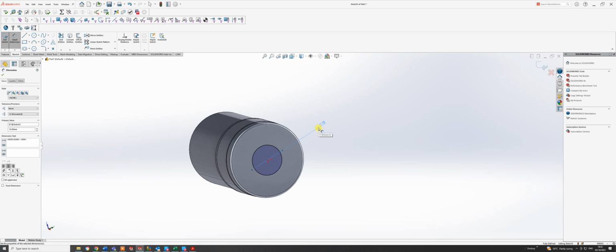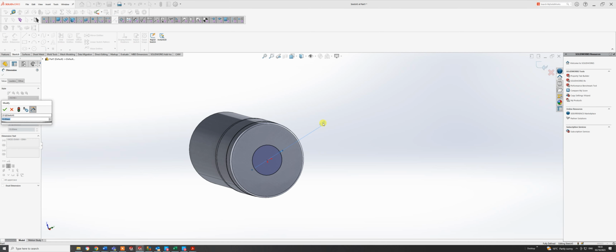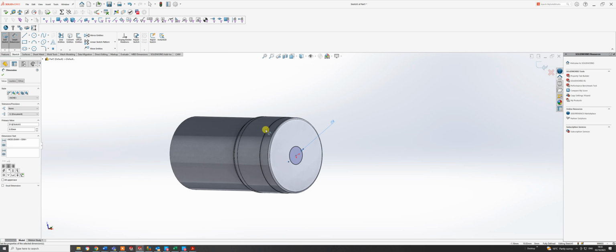It looks a bit too big at the moment. I'm sure I haven't done that, have I? No, I know it's 4. 6. Let's put it at 6mm. So I know the actual shaft is 4mm. Let's do that there. Okay, and I'm going to go to features, and I'm going to go extrude boss base. I'm going to untick this housing here.